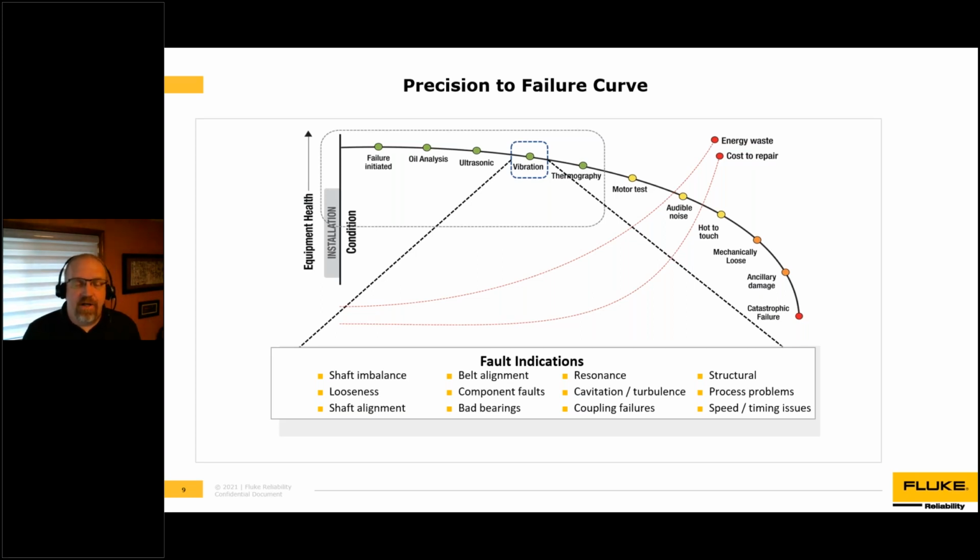Just past vibration analysis, we have infrared thermography. Infrared thermography of bearings detects the later stages of bearing wear, where the bearings start to heat up. And unless you are running those bearings in a run to failure application, that's too late. However, thermography can provide great insights as to the early detection of electrical transmission faults, and simplified thermography tools like IR thermometers are great tools in the hands of your operators doing screening during their daily maintenance checks.